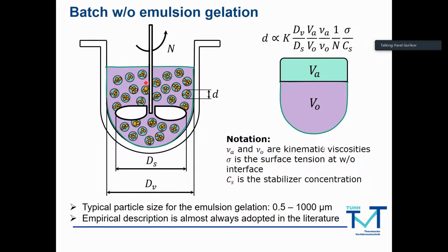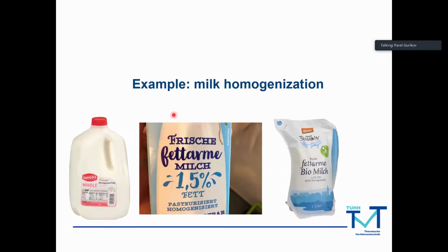So maybe it's not that good an idea to use batch, to use big autoclaves, big reactors, because in these big machines you can't really supply energy, in our case, to break down particles homogeneously. So there's going to be always an energy distribution.